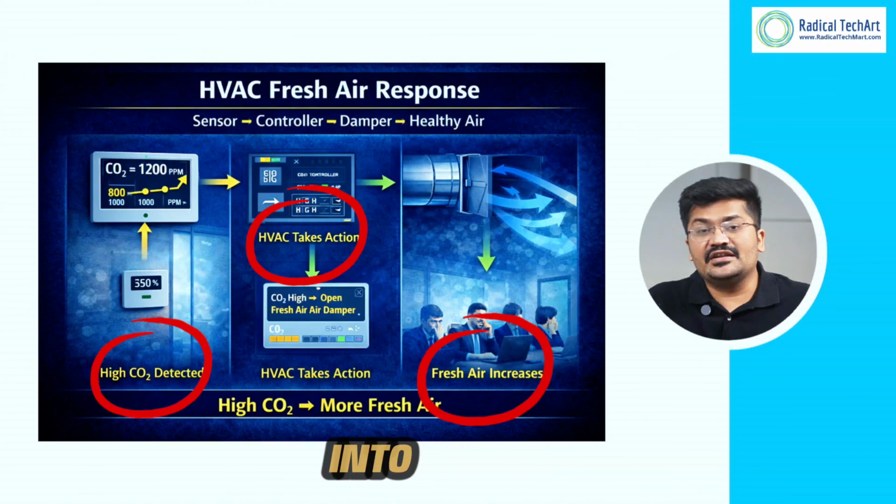Now, many industrial systems use burners and furnaces. These systems require the correct amount of oxygen for proper combustion. If oxygen levels are too low or too high, combustion efficiency decreases. And oxygen sensors help to monitor O2 concentration in combustion systems. This improves energy efficiency and safety.